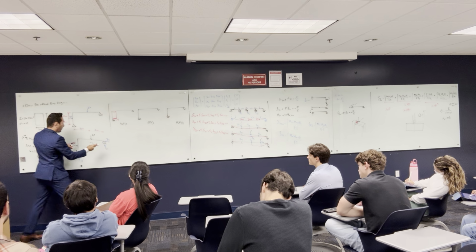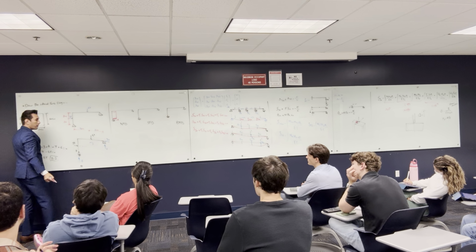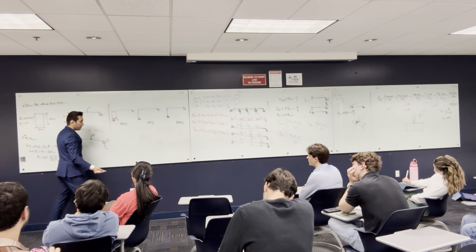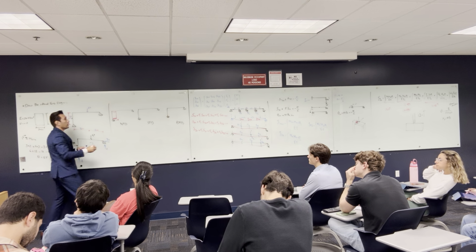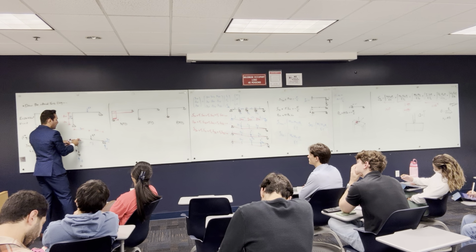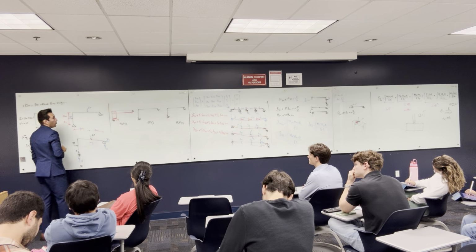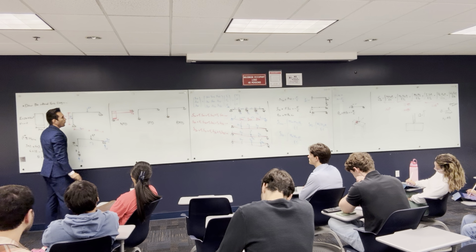How about this one? What is the value of the normal force here? 3. 3, and it's compression or tension? Compression, because it goes inside the section, not outside the section. So I'm gonna have 3, and it's gonna be all the way until I come here because there's no other force. So this is gonna be -3. Okay, I'm done with the normal force.